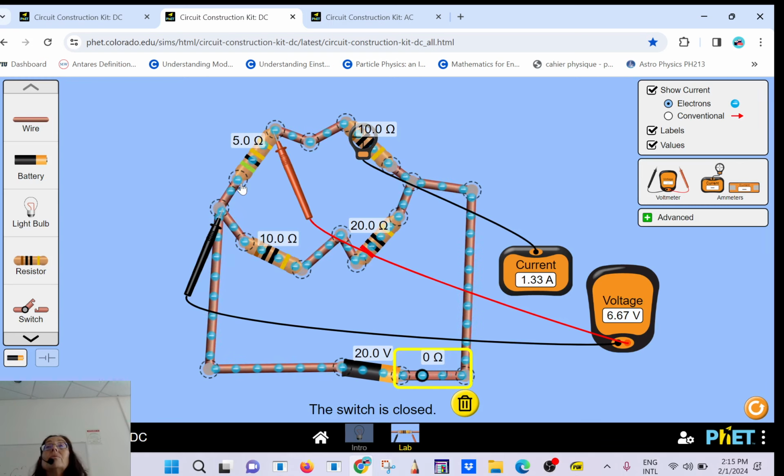Example, here, what's the peak value? 10. Okay, what's the period? So it goes one cycle up and then goes down. That will be your period. 5. Okay, so that will be the equation. Now, if we want to find the frequency, so you see how it's very slow. So it doesn't vibrate very much. In 1 second, you don't have a lot of cycles. How do we find the frequency?